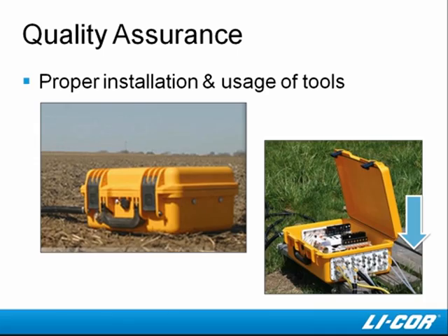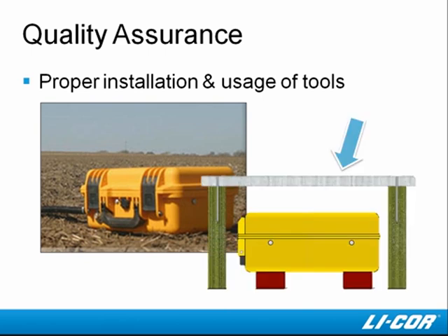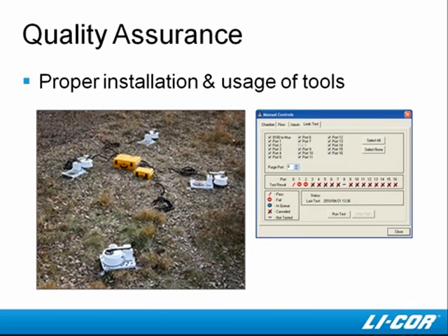Direct sunlight can cause overheating of the instruments. Some sort of shading is appropriate under these conditions. The shading could be as simple as foam insulation nailed to the top of 4 stakes pounded into the ground. And when measuring multiple chambers, the potential for air leaks increases. Therefore, it is important to perform a leak test after installing all the chambers in the field to ensure that there are no leaks. The leak test is covered in Chapter 10 of the manual.